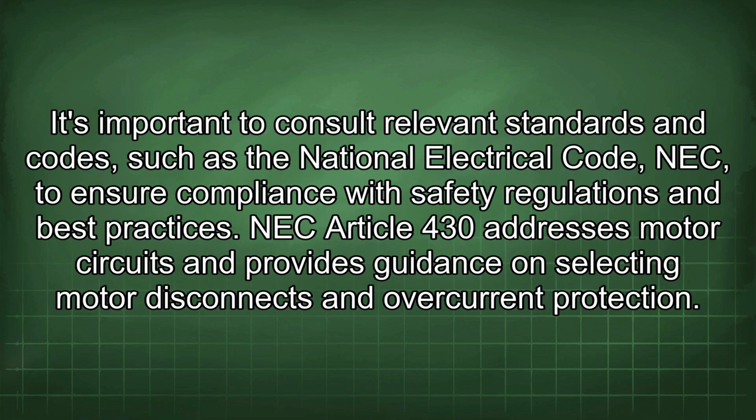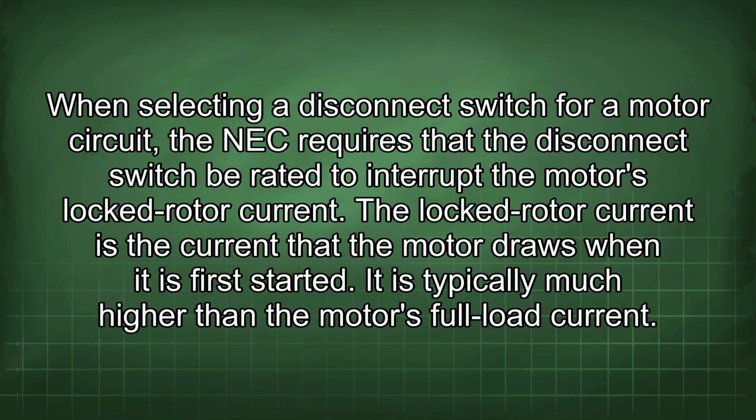It's important to consult relevant standards and codes such as the National Electrical Code, NEC, to ensure compliance with safety regulations and best practices. NEC Article 430 addresses motor circuits and provides guidance on selecting motor disconnects and overcurrent protection. When selecting a disconnect switch for a motor circuit, the NEC requires that the disconnect switch be rated to interrupt the motor's locked rotor current.